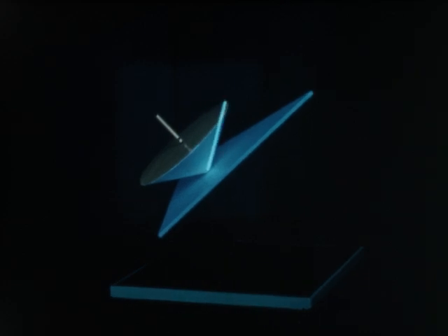first choose a normal to the plane to be used as an axis of revolution. When the given line is revolved about this axis, it will generate a right cone whose base is parallel to the plane. All elements of the cone maintain a constant angle with its base and also with the given plane.